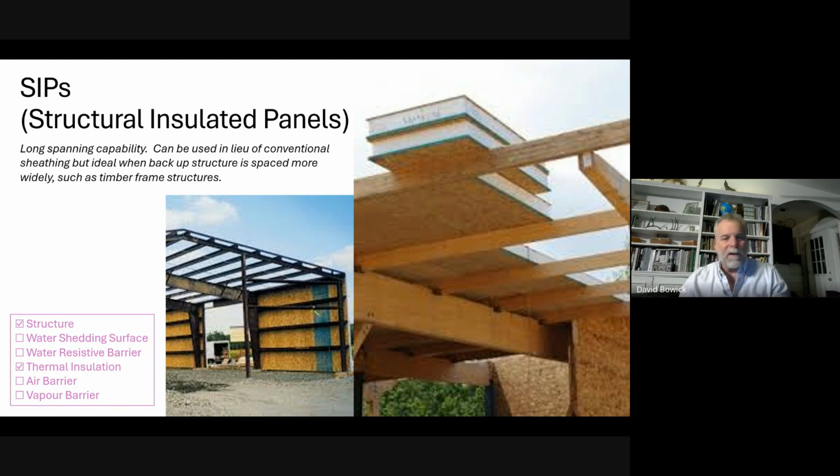unnecessary. So for the structure, we need our floors to carry 40 pounds a square foot. So we'll design to 45 pounds a square foot. We might be at 41, 42. We are getting no value back designing our structure for 100 pounds a square foot if that is not the demand on the structure. So we get no value back. EPS is not the best insulation, but it's good enough. You're better to spend more money making it a bit thicker and having more insulation than using a higher quality insulation product if the lower quality product is going to do the job well enough.